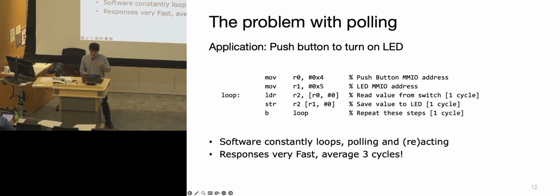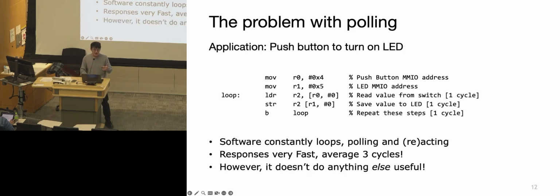In this case, it probably works okay because it's a very small piece of code and it's super fast. Every 3 or 4 cycles, you read that event pin once. And no human being will be able to press the switch or button that fast. But the downside is that you can't do anything else with this program. The whole program is only there for listening to that one switch to go off.